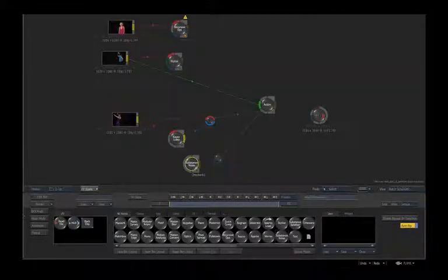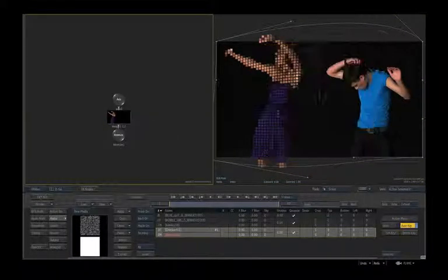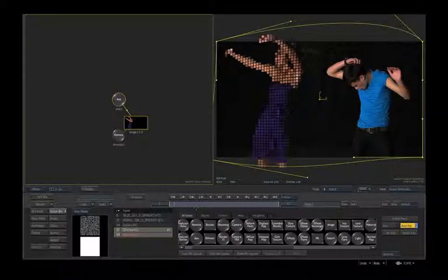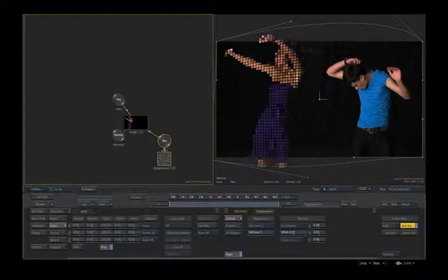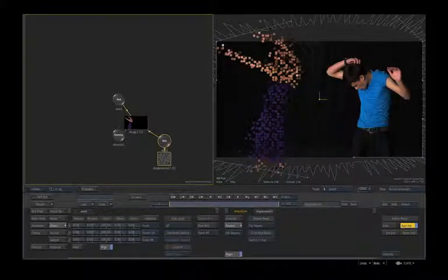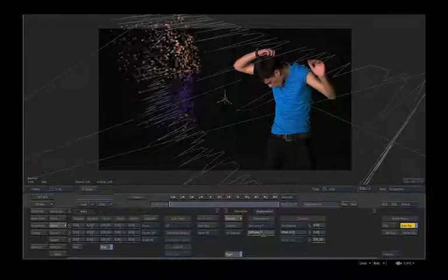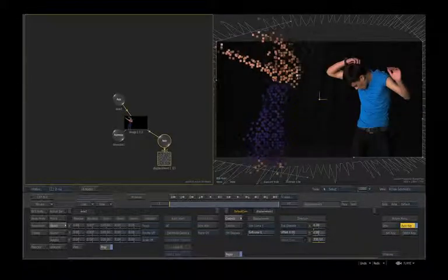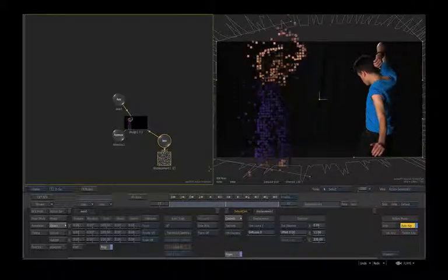And you'll see how I'm going to use this right now. I'm going to feed it in, and we'll just use it not as an image layer, but as a displacement map. So we'll take our layer and bring in this image's displacement. So you're going to start to see what happens when I start moving the pixels around like this. It's just one little cube at this point, so let me just tile it out so it affects everywhere. And you're going to start to get the idea as to how you can have complete control over how these pieces move. And of course, as the footage plays, it's going to move around based on the different position of those dots.